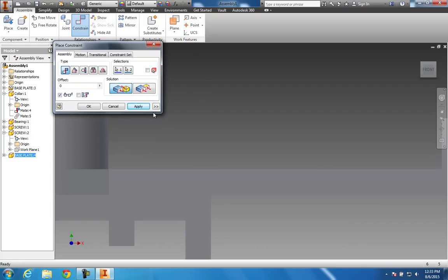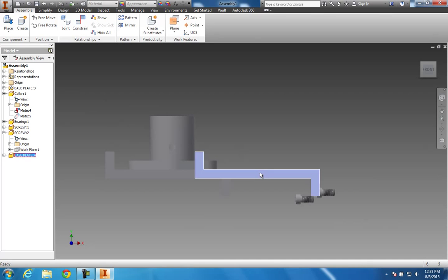It's kind of hard to see it, but see, they're flush together, but mate, it turns this around and mates them together. So you can actually do this, and then sometimes you'll get the wrong one, select it, and you can just flip between them and hit apply whenever you're done. But I don't need that one, so I'm just going to delete it off.